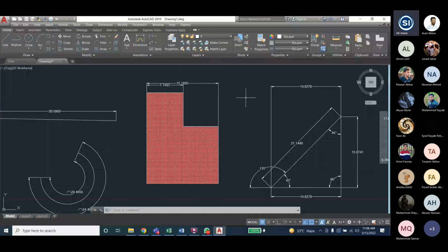Continue means now you can see here, in the continue it is starting from this point. The end point of the first drawing is the starting point of the second. But here in the baseline, you can see it is taking the total distance, for example from here to here. But in the continue, it is only taking the distance of the next half. This is the difference actually.